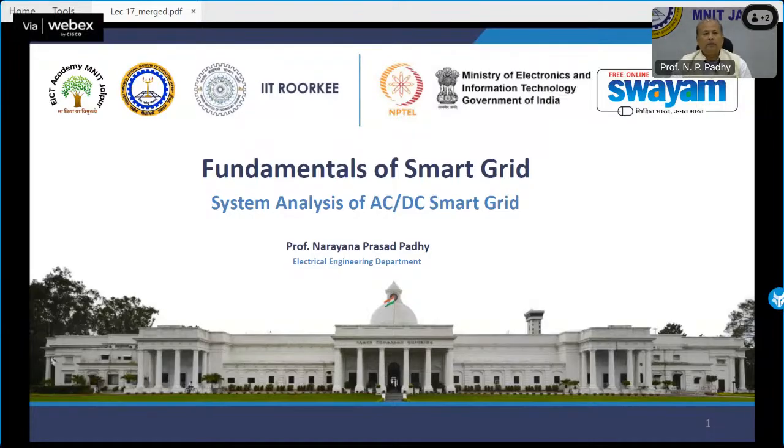Okay. So why is the AC/DC microgrid important? Because as of now, we talked about a lab-based pilot where we have a single bus, and we connect my DC load, my AC load, my DC generation, my AC generation, everything clubbed. But that is simply laboratory experimentation, operation of a microgrid. If I go to reality, the distance between my PV panel and my diesel generator is probably 300 meters. So there is a cable connected.